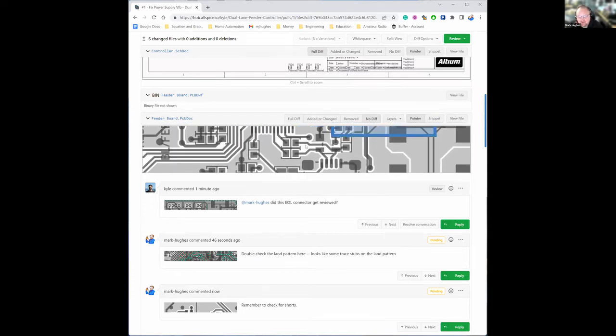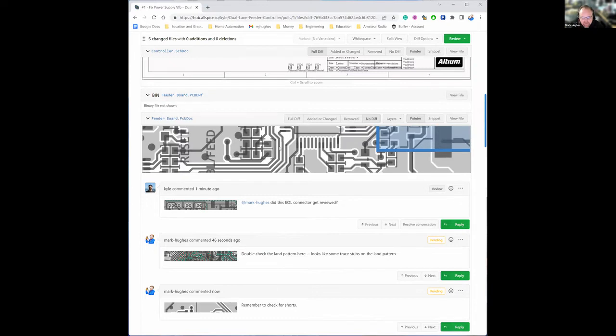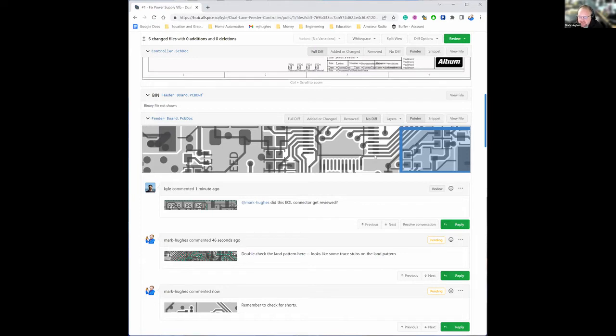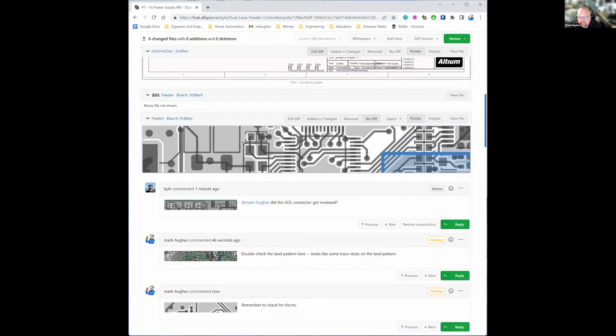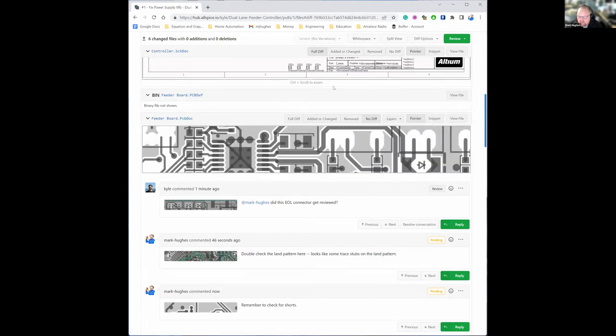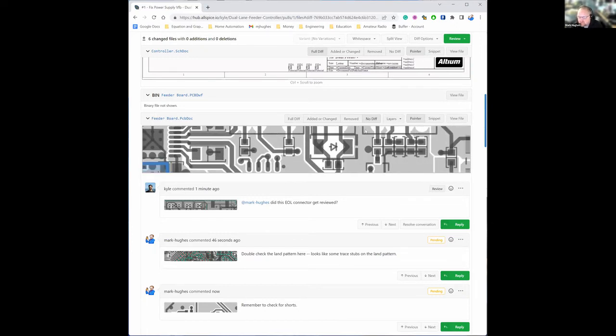The things are going to be too close together. It's going to be too much of a pain in the butt. Nominal's fine. The most land pattern overhang condition is when you make these land patterns as big as you possibly need to make them, and that's real easy to rework. But it kind of leaves a little room left over on the board. So nominal's good. Only do the least if you're doing something like a smartwatch and you just don't have the space.